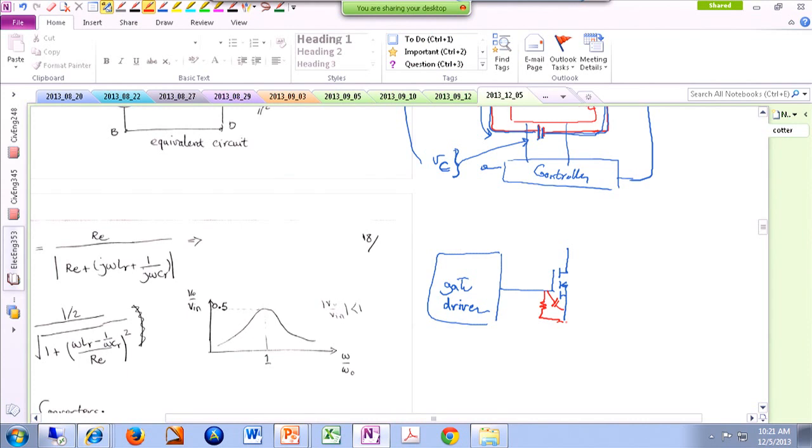So what this resistor does is, it doesn't interfere with the regular operation of the system, but if you turn the system off and keep the transistor on, it gradually discharges this cap, and gradually after, I don't know, 10 milliseconds or so, for instance, this turns off. So this is just for protecting the system, that you have turned the switch off, you have turned the power off, assuming that everything is off in the system, but some of the transistors in the system may still be on. And in order for this cap not to interfere with the normal operation, it's usually in the order of like kiloohms, like let's say 10 kilo ohm resistance is a good one over here.